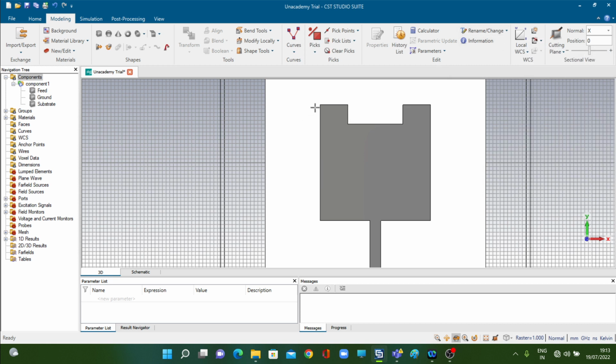Now suppose this current flows from here to this point. Previously it was traveling a distance of 30 millimeter. Now what will it do? It will come from here to here to here, then here to here to here, and to here. Why? Because the current can't pass through this dielectric bridge. It has to follow a metallic path only. So this portion is removed. That means the current cannot have the straight line of motion now. Instead, it will follow this loop.